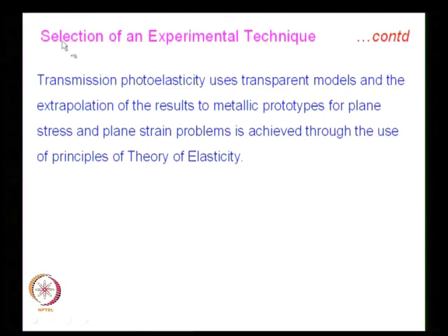But from the point of view of selection, if my problem on hand demands stress analysis interior to the body, then I would find out whether I could go for 3-dimensional photoelastic analysis, because a certain class of problems you can handle, a certain class of problems you will not be in a position to handle. Transmission photoelasticity uses transparent models, and the extrapolation of the results to metallic prototypes for plane stress and plane strain problems is achieved through the use of principles of the theory of elasticity.